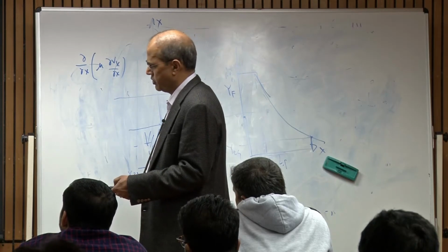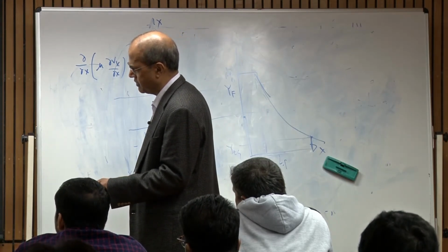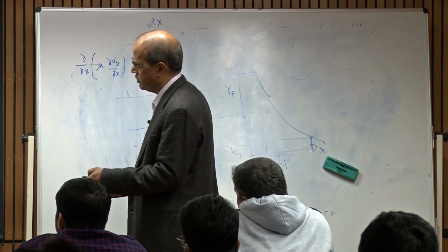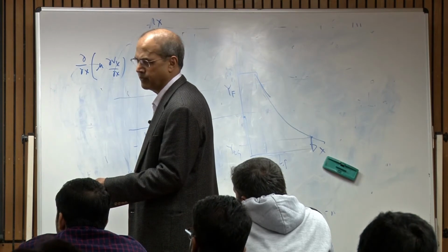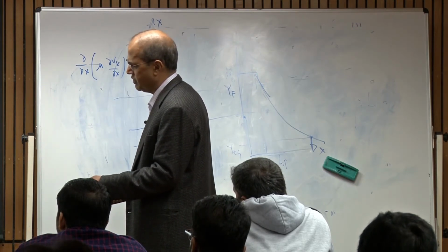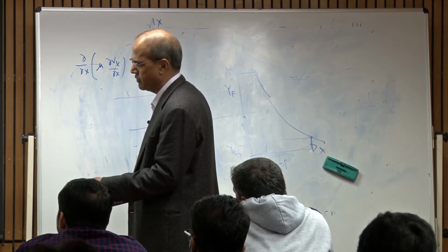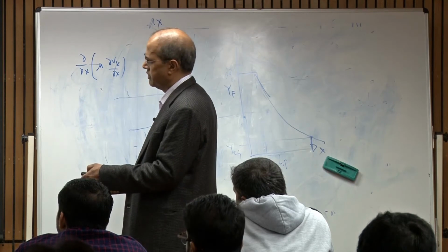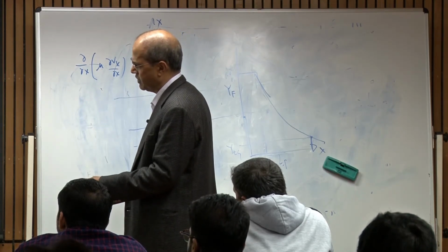Okay. So, this is the axial convection or radial convection. Okay. You see, you can basically replace this Vx by yi, so you get the same term. Okay. Then this is the radial convection. Again, difference is Vx here, yf here. Okay. This is the radial diffusion of momentum. This is the radial mass diffusion.